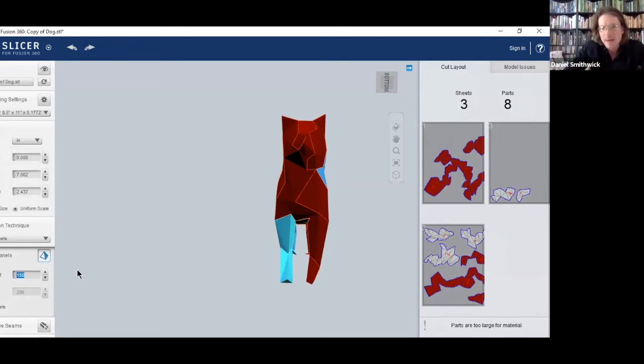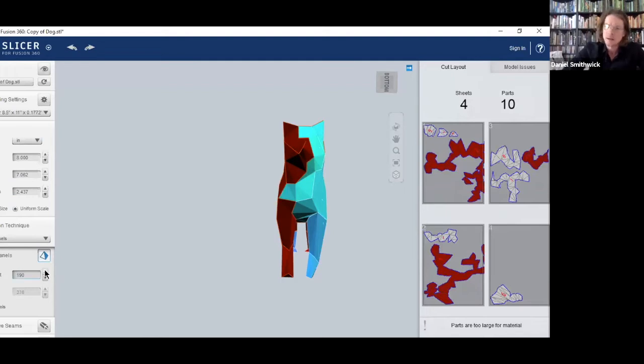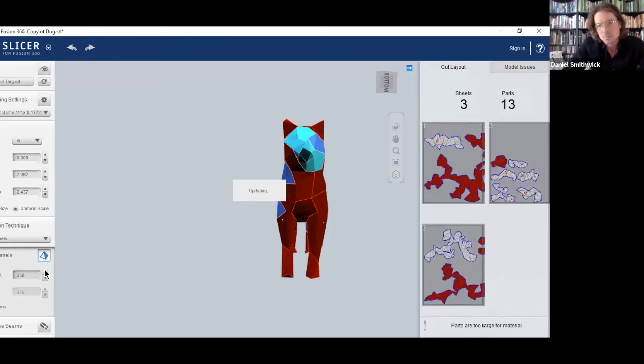to fit. It's not perfect, and sometimes you will run into, I mentioned this earlier with TinkerCAD, and you kind of ran into this, Katie, that the file was probably pretty big, and maybe caused your computer to crash. Some files can do that, so be careful of opening a really big file in Slicer, because it will just keep doing cycles until it completes it, and sometimes that'll eat up all of your computer's memory. So just beware, some TinkerCAD files are massive and have a lot of detail in them, so just be careful with that.